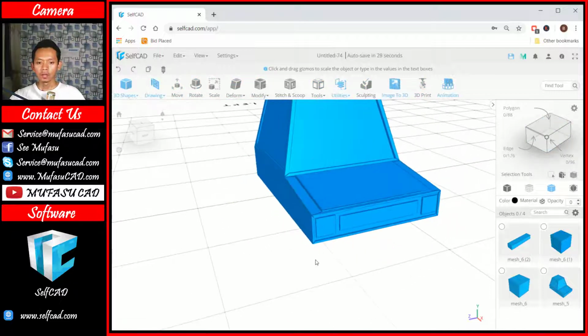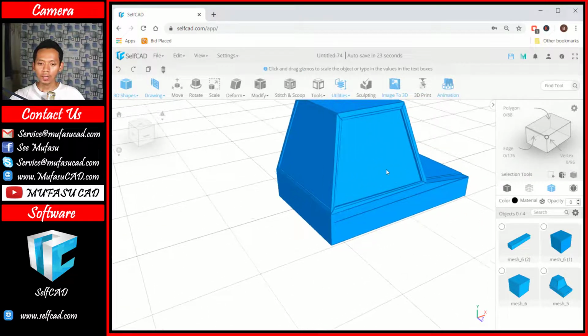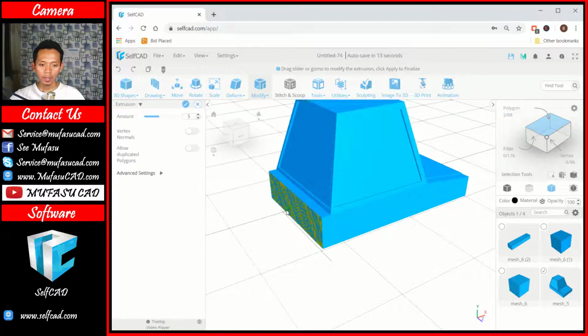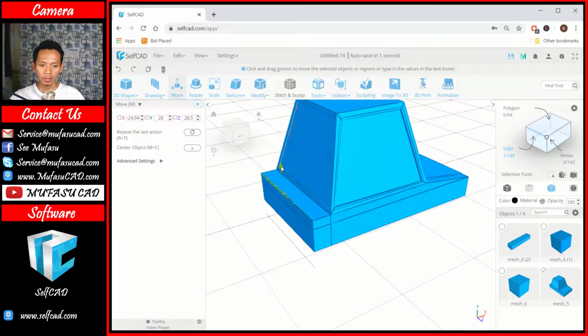Okay, now in the back I will use polygon again. You can select these objects. You can click the polygon option. You can click at this surface, and in here I will use extrusion. Okay, we can extrude into here, and then I will use the edge option. You can click edge, and then I will select this edge. You can use the move tool. I will move in the green axis to the bottom here. We select again this edge, and then we can move to the top a bit like this point. Okay,